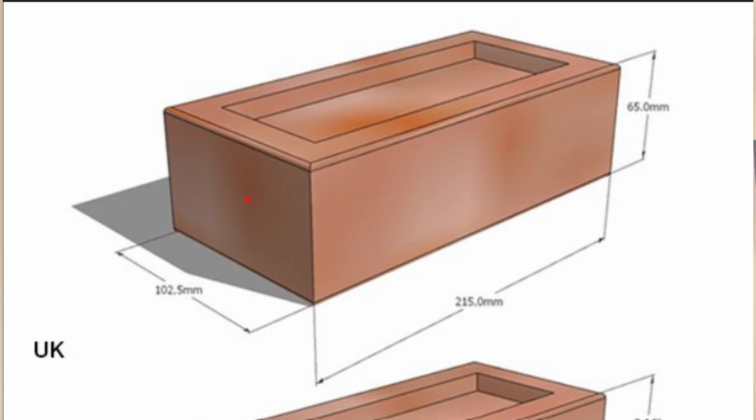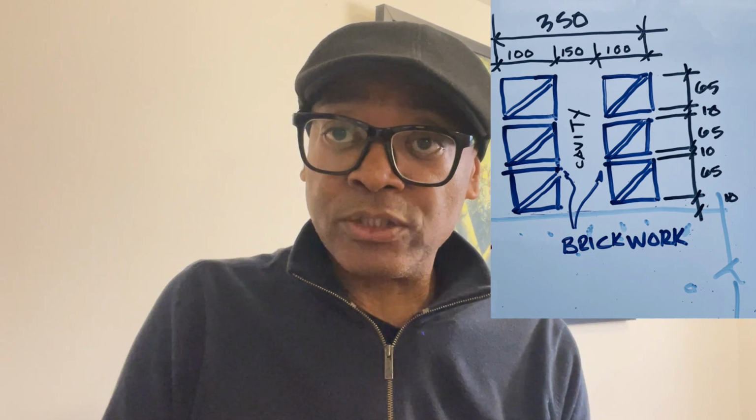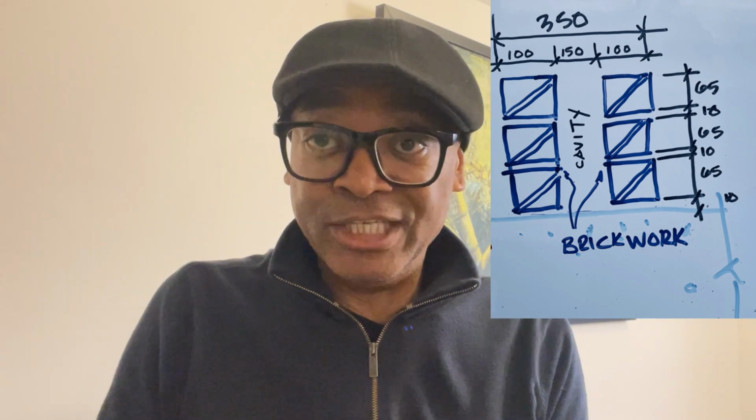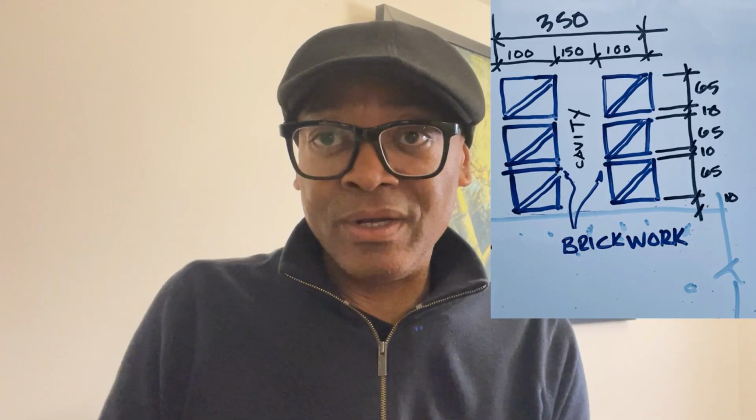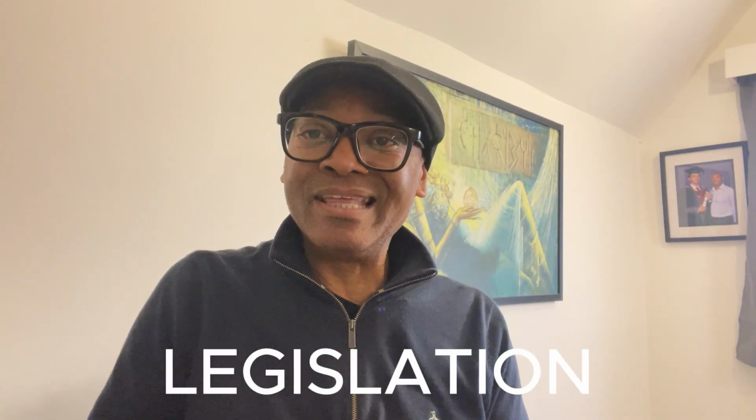I know they're 102 millimeters, but really made simple, we're talking about 102 millimeters wide. This is no joints on this. We're talking about a cavity, which is a gap of 150 millimeters, and then another engineering brick to the inner skin of 100 mil wide again. So overall, you have a nominal cavity of 350 millimeters.